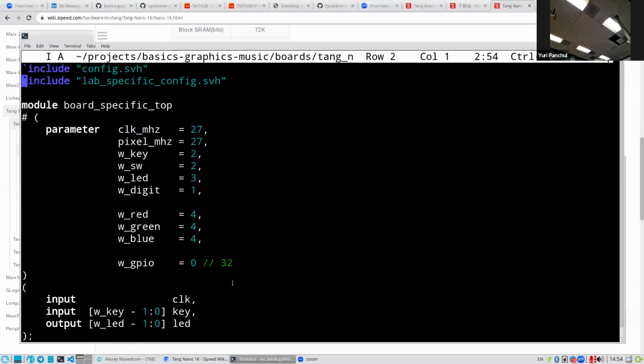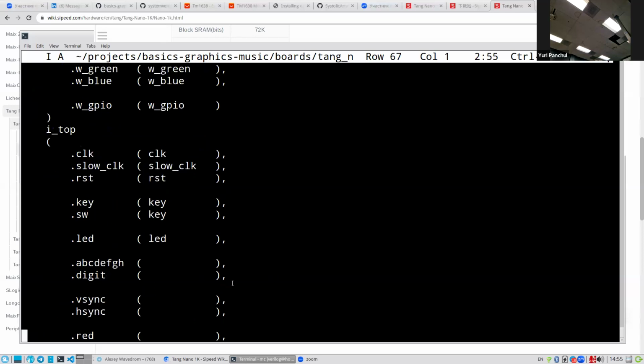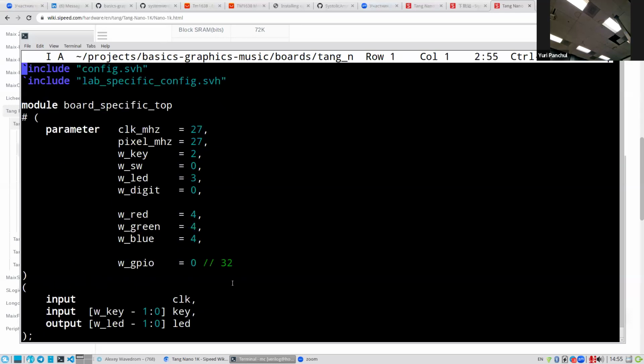And in fact, first of all, let's see what kind of error it gives if you put number of switches 0 and number of digits 0, because it will make an error. Gowin is supposed to make an error. If it doesn't, it's strange. Some tools just treat it as a negative subtract, like a port from -1 to 0, which is a 2-bit port. But let's see whether Gowin can handle it, because this will be optimized away anyway.